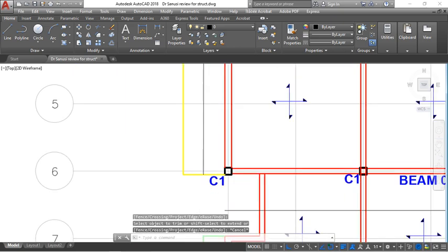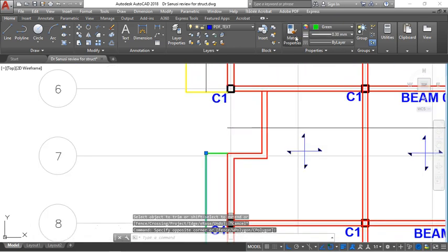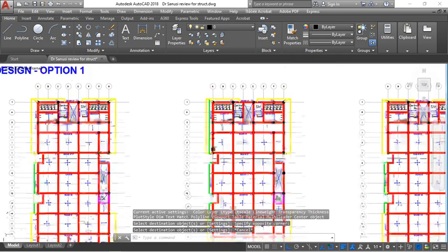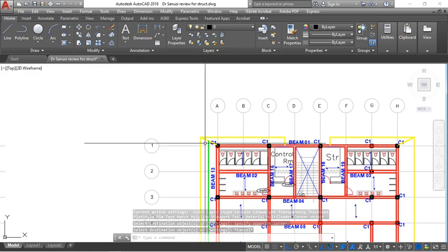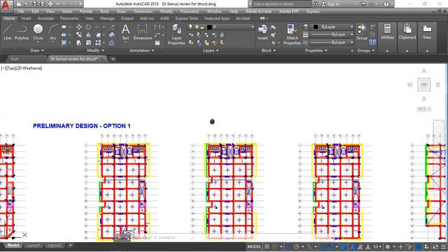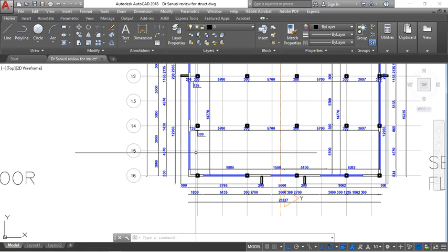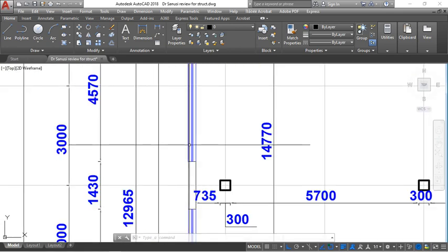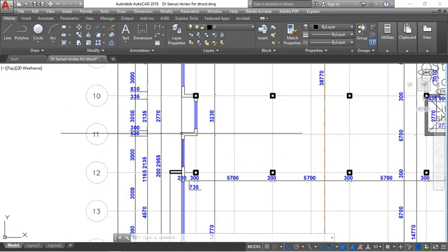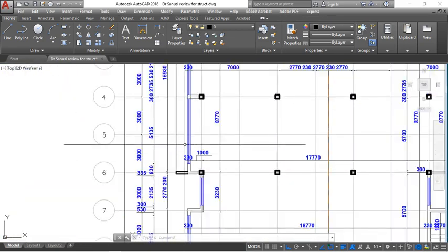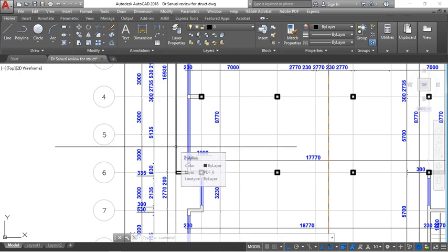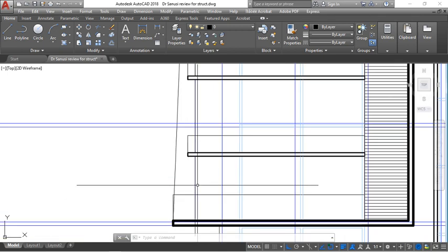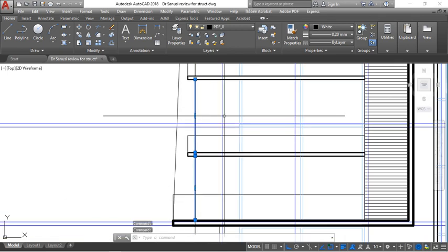That was why I left it, so that we can look at it together while I'm making the video, so the slab does not actually extend up to this point. This is where it extends up to on the second floor. Which means that the slab is only the slab that will support this wall area on this side. So the slab does not extend up to this point, which is the cantilever as shown here. It only extends up to the end of this wall.